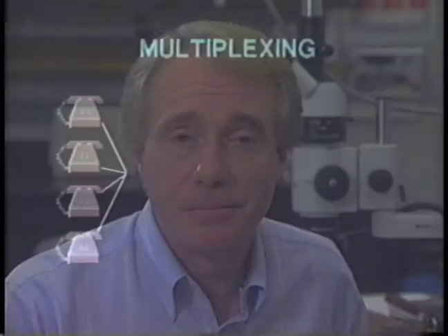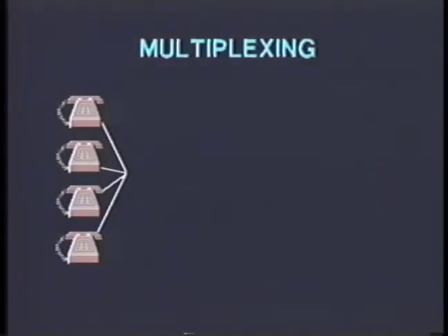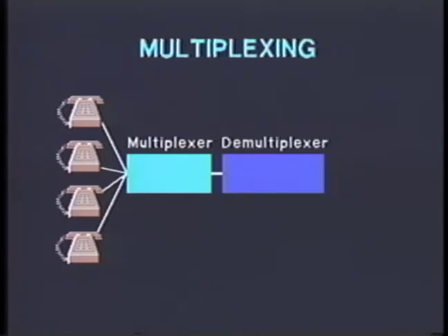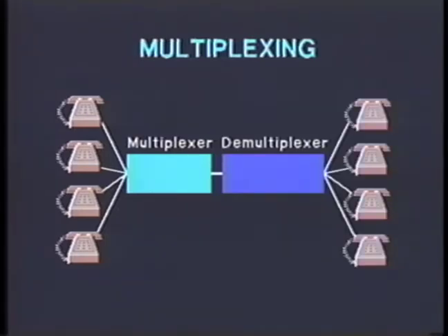Only one signal can be transmitted over a given medium, whether it be a wire, microwave radio, or fiber optics. Multiplexing is a technique used to combine many signals into one composite signal. The composite, or carrier signal, is transmitted. Then demultiplexing separates the composite into the many original signals. Different techniques are used to multiplex based upon whether the signals to be multiplexed are analog or digital.